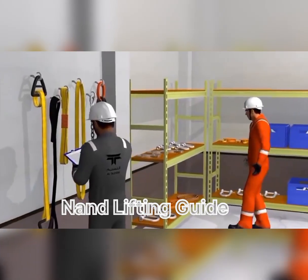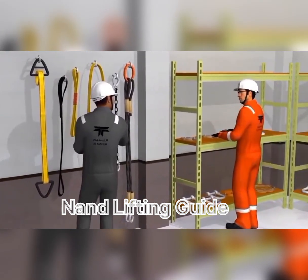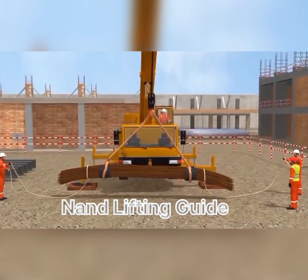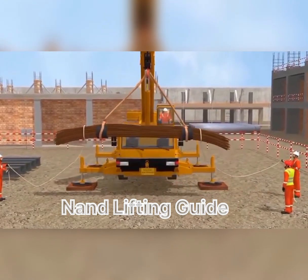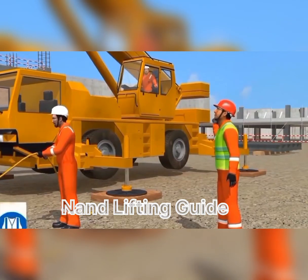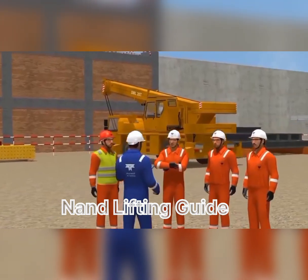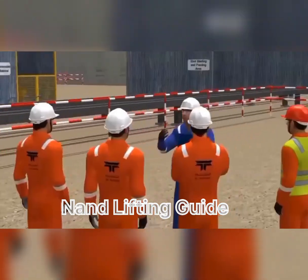All the lifting equipment should be checked by a lifting equipment controller every month, and it shall be inspected and color-coded as per the current month's color-coding practice. Every lifting work to be carried out should be pre-planned and shall be conducted under the careful supervision by a competent person. The personnel responsible for giving signals, banksmen, should wear reflective vest for allowing their identification. Before starting the work, a permit has to be issued in accordance with the safety norms of the company.